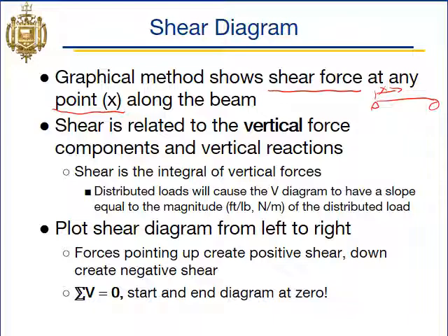All right, so how do we make our shear diagrams? Well, we're going to analyze all of the vertical force components, whether they're applied or reactions. And the shear diagram is the integral of the vertical forces. So don't worry, calculus sounds hard, but it actually works out to be pretty easy. So we'll go through this.